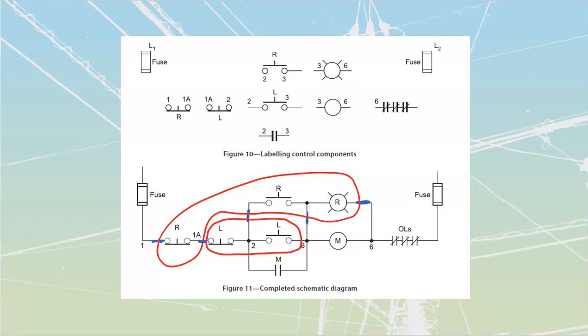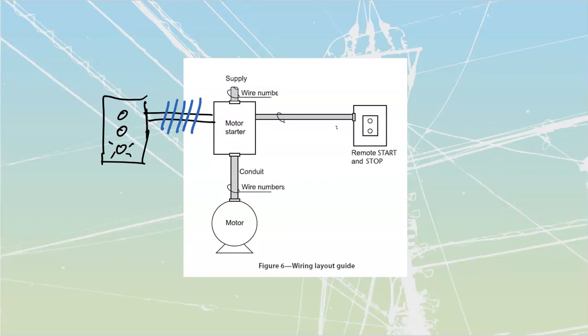This one you've got to be tricky on because you do have some wires that are poking through with the same wire twice. This is a distinct wire poking out over here. Okay, so I'm going to have a green one over there. Wire number 2 pokes out in 2 places. I only count it in 1 place because I can make all the other junctions inside of the other box, and then wire number 3 comes out over here. You just need to be careful with this one over here. Yes, I see that I've got that line poking out up top there, but because it's the same line that we've already accounted for, we don't need to worry about that. So I can take it back to this, and say how many wires do I need? 1, 2, 3 that I'm going to need to have inside of that conduit over there.